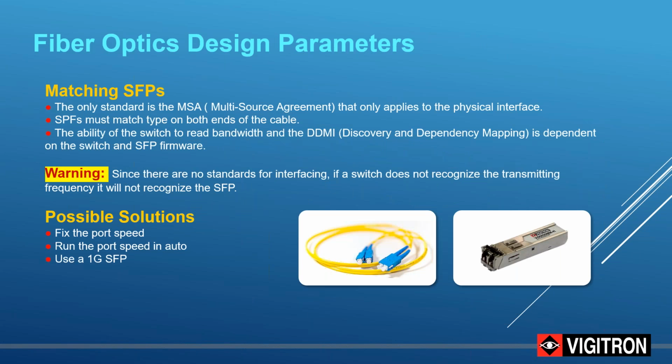Fiber is unique in this. And the first thing we want to say about fiber is glass. Fiber is used because it rejects a lot of signals, because it rejects the ability of transmitting surges. And for all of these reasons, you cannot transmit PoE over fiber. It's not possible.